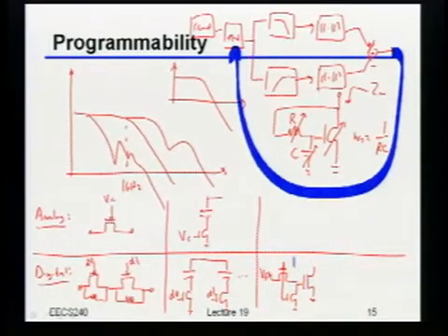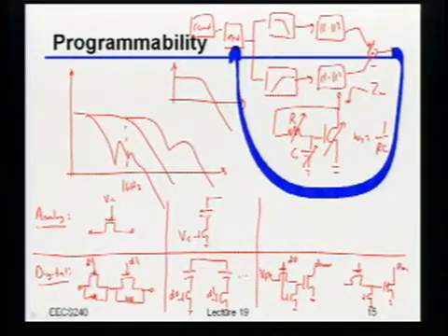And so then you could take this whole thing and repeat a bunch of them in parallel. So let's call this, let's say, D0, and let's call this the drain. Right, you might have another one that looks like, let's say, that. That's also the drain. And this is, let's say, D1 and V feedback, right? So you can take a bunch of those, basically partition them into different pieces, and then turn on and off how many of those different pieces you actually use in the feedback circuit.